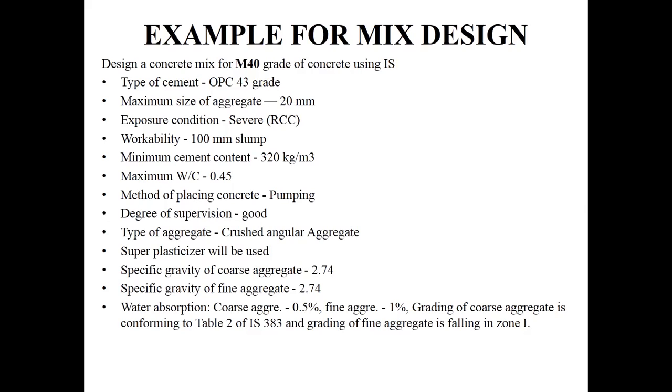We know that if you are going to construct high rise buildings or tall structures, say G plus 6 or G plus 7, you cannot carry the concrete mix to the top floor. It will be a little difficult. By that time, to transport the concrete we will be pumping it. So the method of placing of concrete here is also taken as pumping. If it is pumping, the workability will be a little higher than normal placing of concrete.